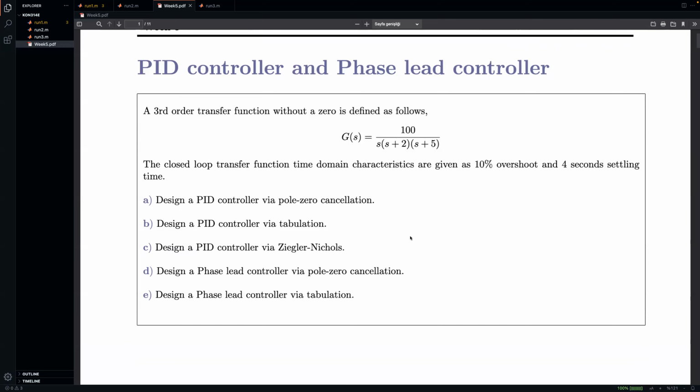So it's quite an experimental design method in the time domain if you think about phase lag controllers, but a phase lead controller can be designed using the algebraic method. Most of the time we don't use a lag controller with the algebraic method. It doesn't mean that you shouldn't, you can, but most of the time that's not the way of doing it. We just add it near the origin and it works magically.